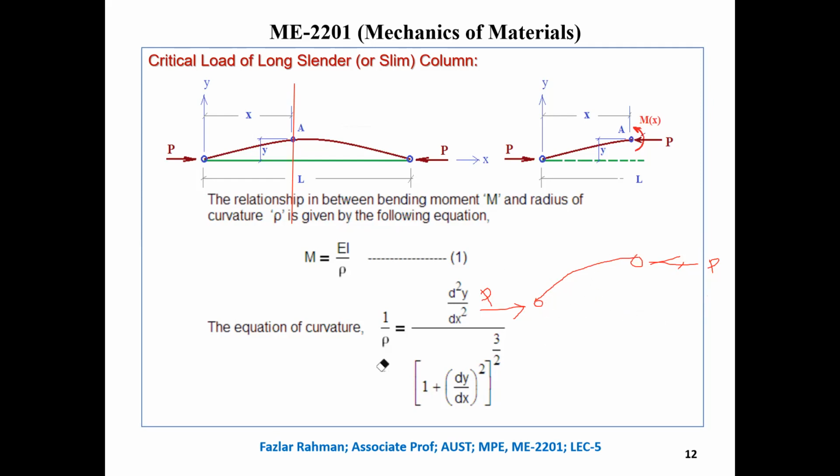So you need to put some rotation, I mean moment, to protect it. You stop it by a clockwise moment, which I call M. Now, how can I figure out the value of M? You take moment over here. If the vertical distance at this point is Y, then M will be P into Y, right?